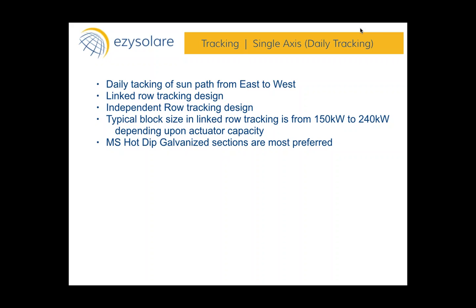See, material science has really taken a toll on the structure part. Initially, 2 to 3 years back, we used to have Teflon coated bearings. They are still being used and still functioning well, with no reported failures on the operational part. Then once again, even bearings have gone through a cost optimization cycle. So gunmetal and MS Bright was introduced by one of the vendors, and special self-lubricant polymers, which are even an advanced version of nylon, are being used. All these new things are able to achieve the 25 years.